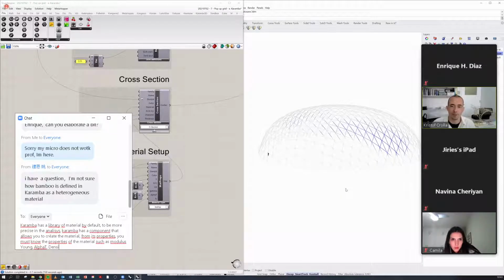It's definitely a ballsy move, but before they made the Mannheim Multihalle, they started with a smaller-scale mock-up. I spoke at one point with an engineer who worked on that with Frei Otto back in the 70s and 80s. If you take a bubble shape like this and put a point load on it, you'll see when it starts to buckle. You know exactly at which point it starts to buckle.